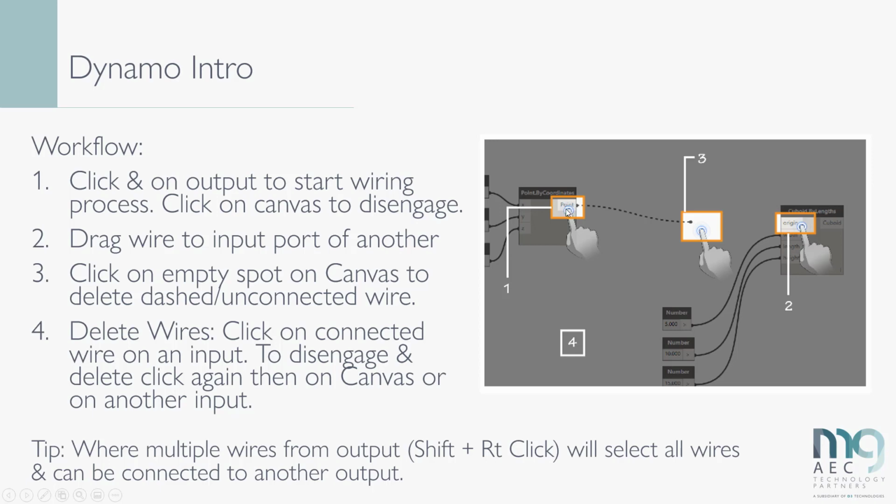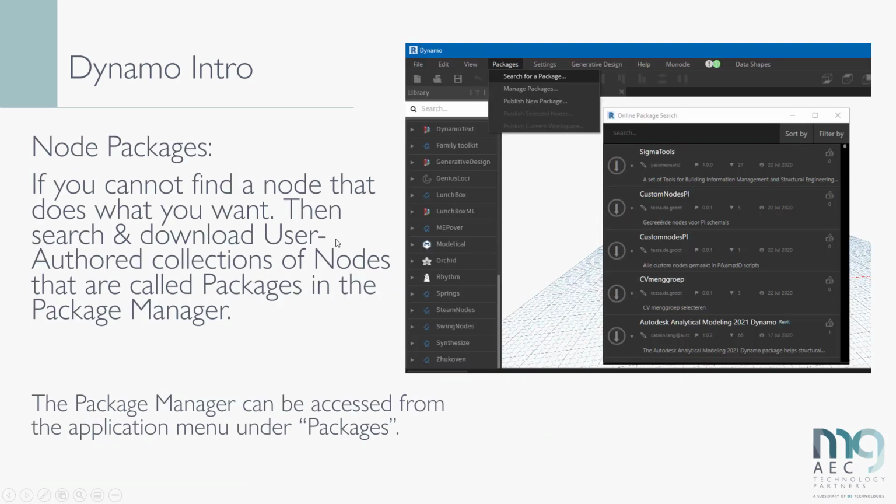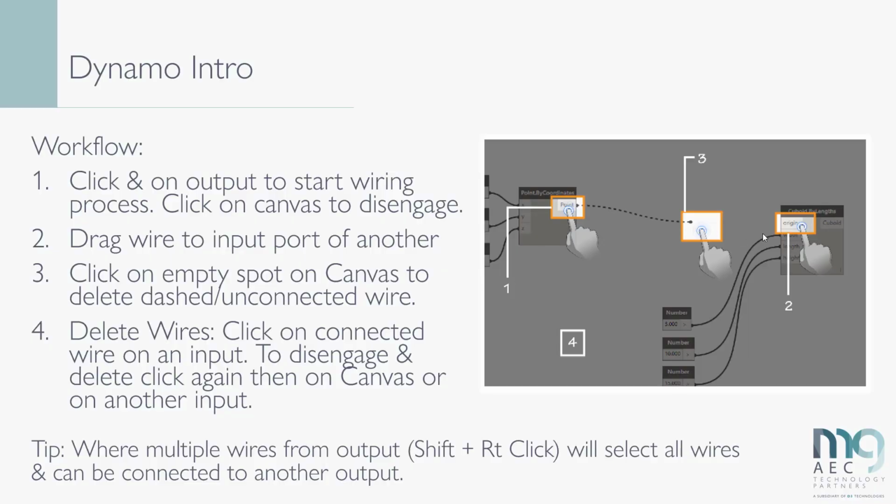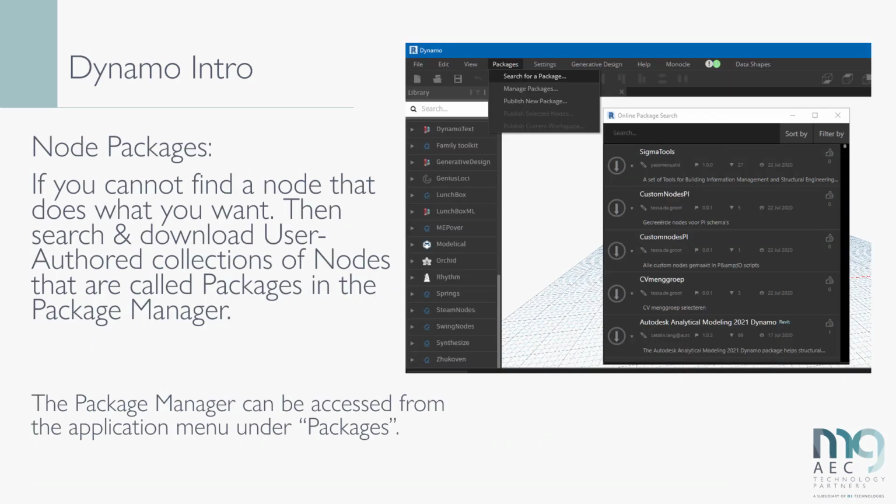And so the workflow here, as we saw, is a left to right workflow where we drop the node and then we drew those wires connecting it to another node. If you want to undo a connection, you need to click on the destination node and drag it out into open space; that is how you disconnect or delete a wire. So we're moving left to right, dropping in these nodes and connecting them with these wires.